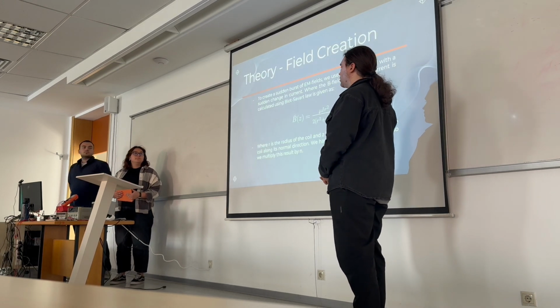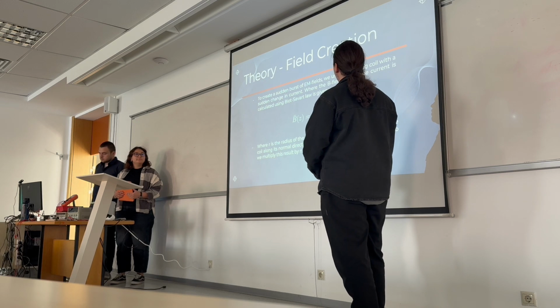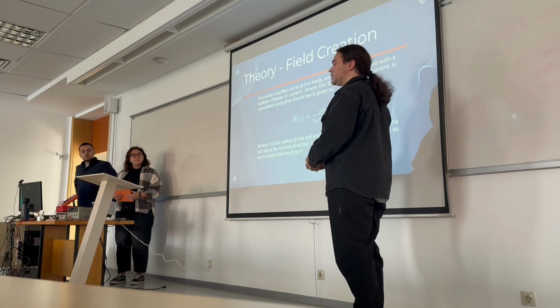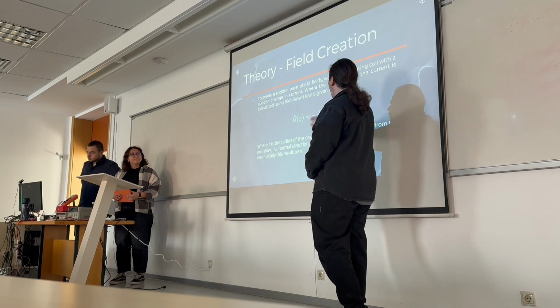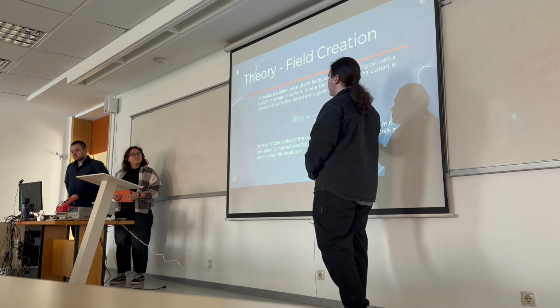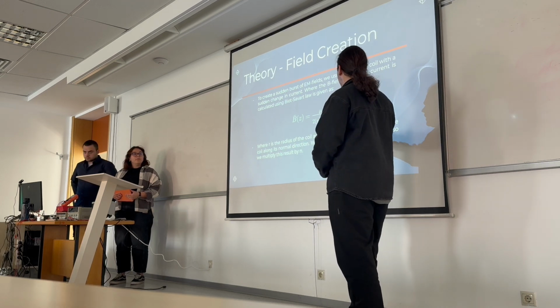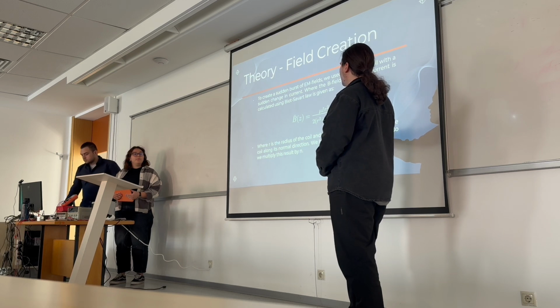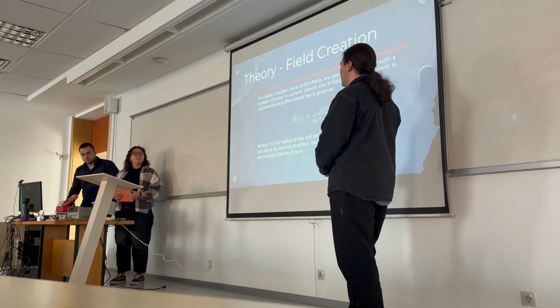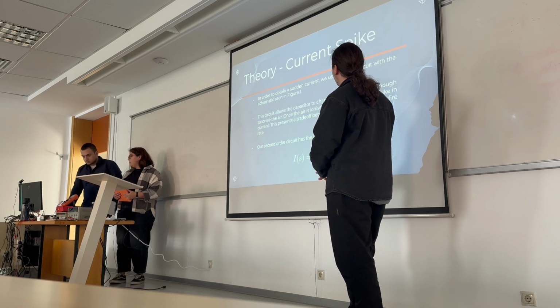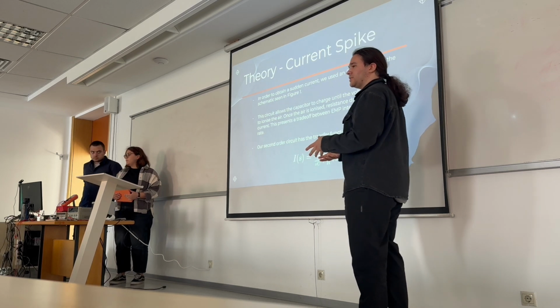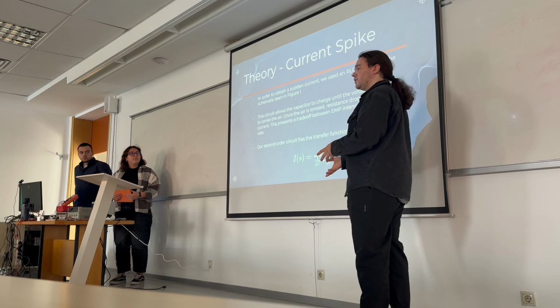As we said, we need to radiate B fields. We will use a coil which radiates B fields with sudden current changes. The B field per current can be obtained from this formula using the Biot-Savart law. And we have 80 windings on our coil, so we will have 80 times this magnetic field. And to obtain the current in question, we need to charge the capacitor as discussed and discharge it quickly.